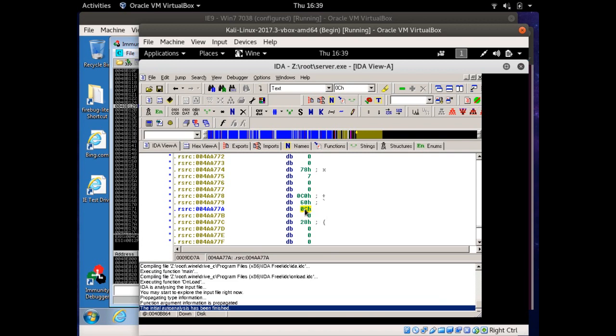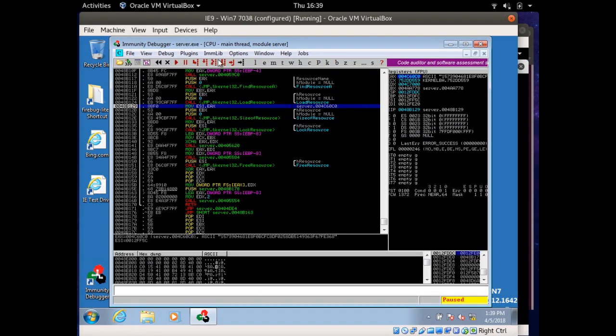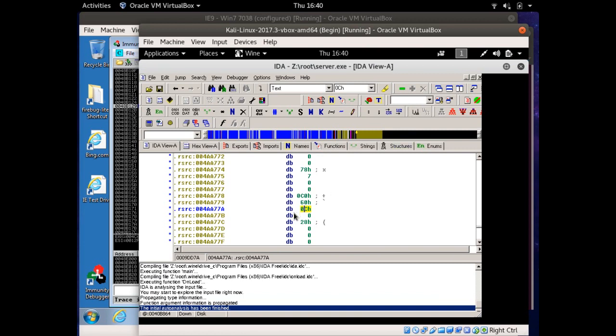You'll see here that's almost similar, at least these two bytes. These two top bytes here are the same as the lower two bytes of this one right here. And in fact, C is the same too. So what it really gave us is an offset in the program memory of where this other hexadecimal string happens to be living.